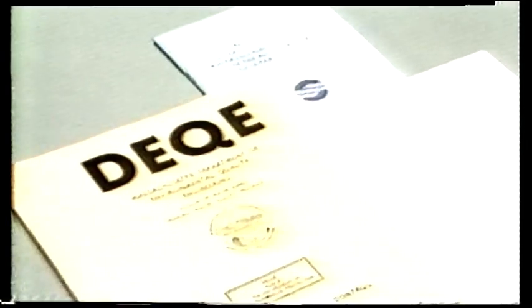The survey team should submit the final report to the facility representative and the local water utility. If the installation of backflow prevention devices or assemblies is recommended, these recommendations should be based on the degree of hazard. Any specific requirements regarding installation, such as state and local codes, should be referenced. Compliance deadlines and the notification process will also be determined by state and local requirements.